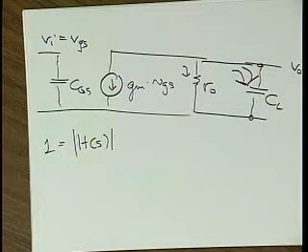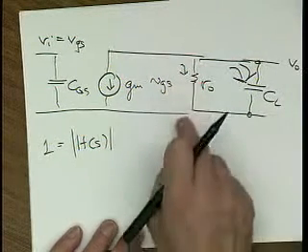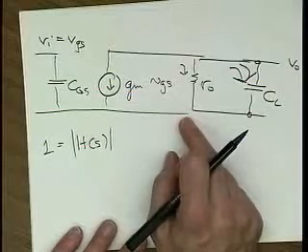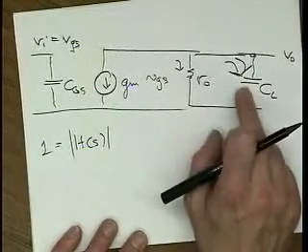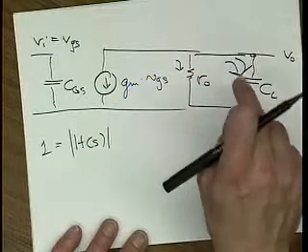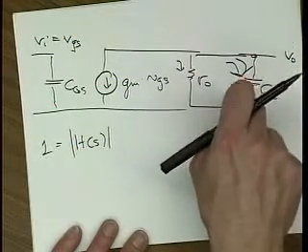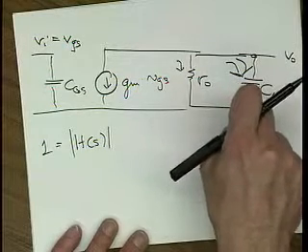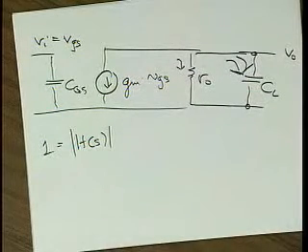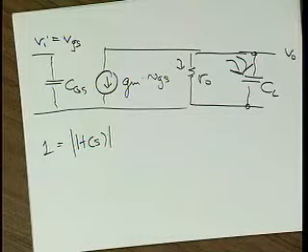Now, because we know this current here didn't change, right? This doesn't change at all over frequency, but suddenly the total current flowing went up by a factor of 100. That means that the current flowing here has got to be 100 times larger, about AV0 times larger than the current flowing here. You know what this tells me?